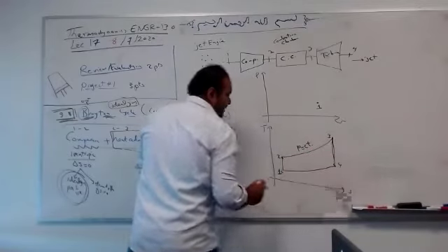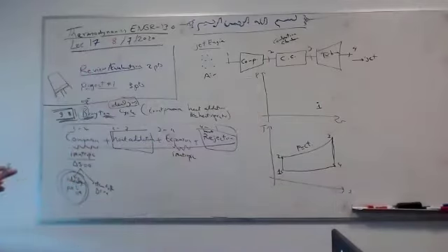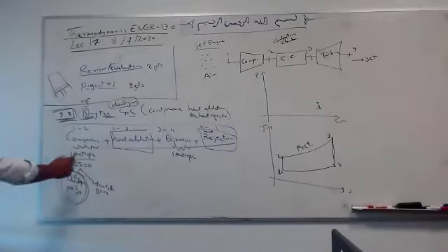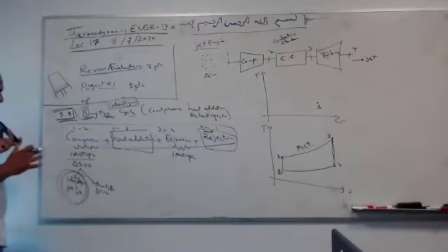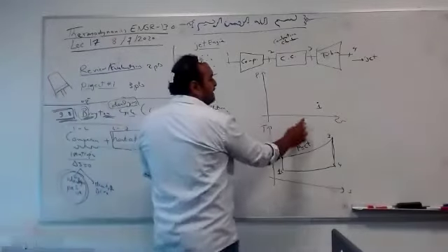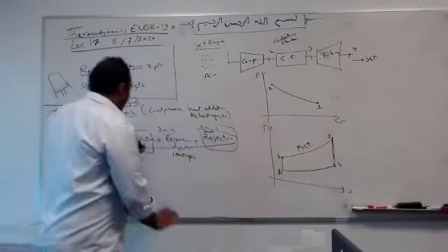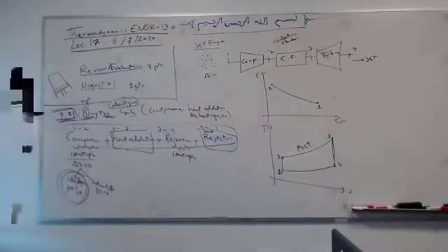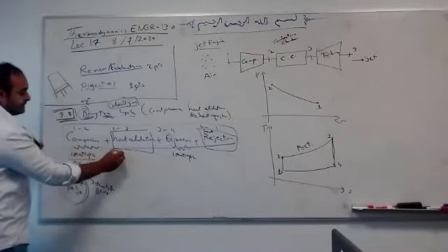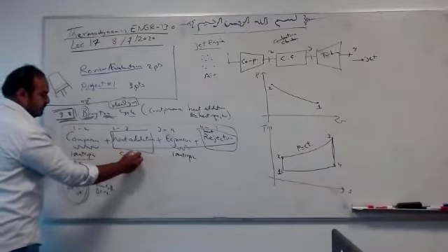Today, I'm gonna discuss the most important physics in this problem. Why you are getting work. If you plot the PV diagram now, this is isentropic. I'm compressing, so the pressure builds up, the volume decreasing, of course, like this. This is 2. Then I'm getting heat at constant pressure. How does it look, guys? Is it vertical or horizontal in the PV diagram? Constant pressure. It's horizontal. Exactly.